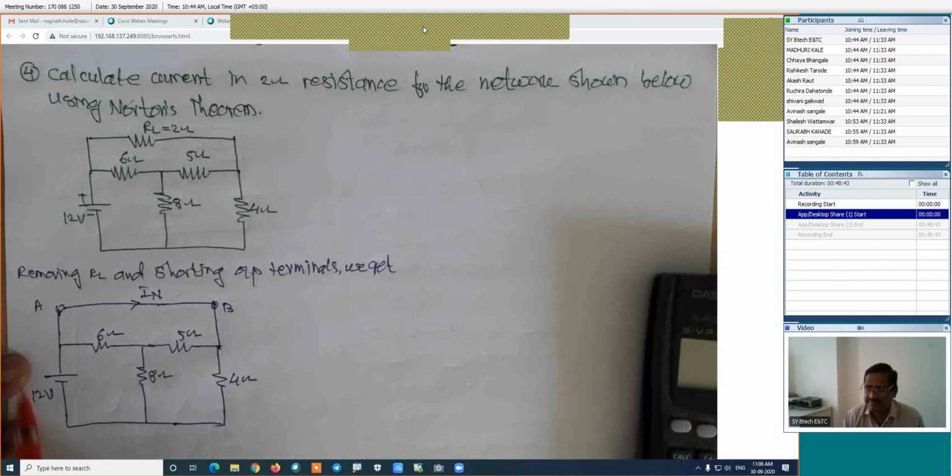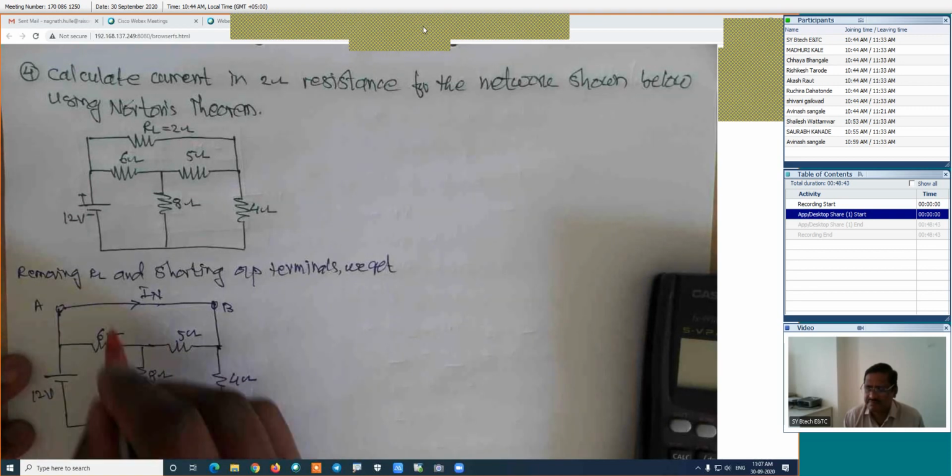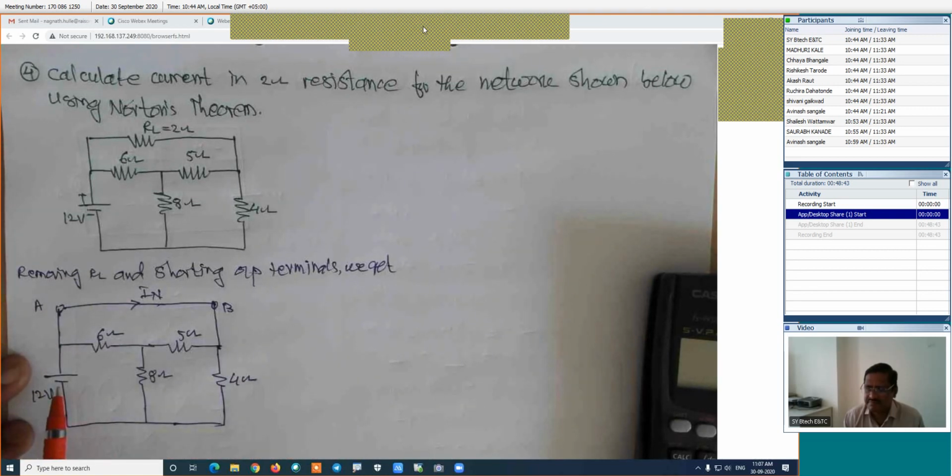Again, whenever we have this complete path is the short circuit, never use the nodal analysis method. In this case, we can use the direct inspection method. This is 1 loop, 2nd loop, 3rd loop, because we have only the independent sources and voltage sources. Only voltage sources, then we can use the direct inspection method.